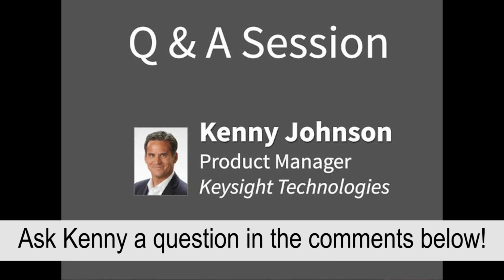Sorry about that. I had myself on mute for a second there because I didn't want to talk over you while you were doing the surveys. So the highest bandwidth for the differential probes is in our family of InfiniiMax probes. The ones that I referenced go to 13 gigahertz, or that I was showing today with that extreme temperature, but we've actually got a family that goes up beyond 30 gigahertz. So if you're out there at those ultra-high bandwidths, yes, we've got probes that go in excess of 30 gigahertz of bandwidth.